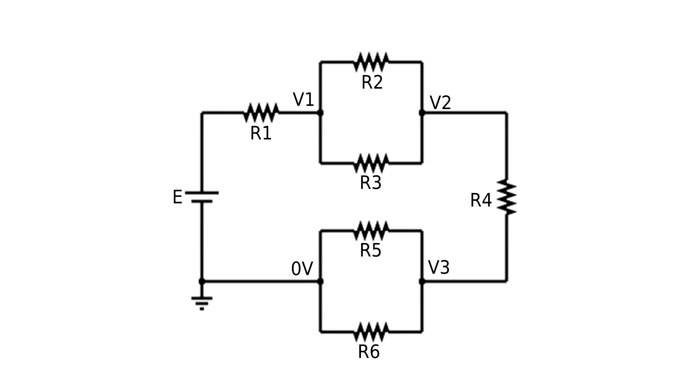The next step is to assume the current directions. Now, it doesn't matter if they're right or wrong in the end, just as long as it's a consistent direction the whole time while you're making the equations. If it does turn out to be the wrong way, you'll just get a negative value, but the magnitude of the current will still be correct.